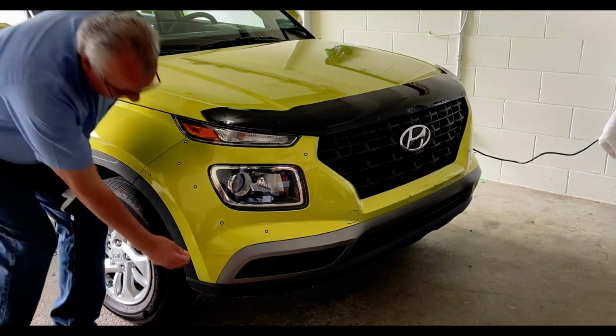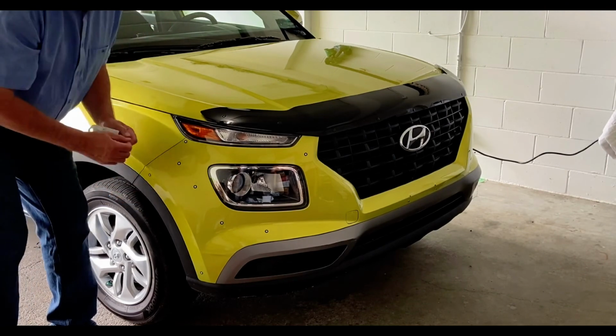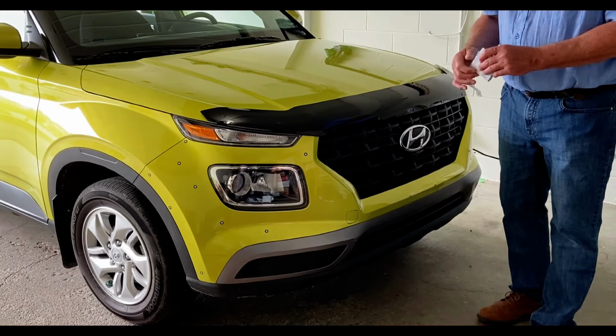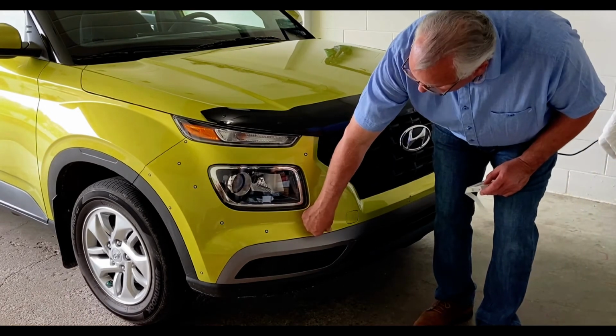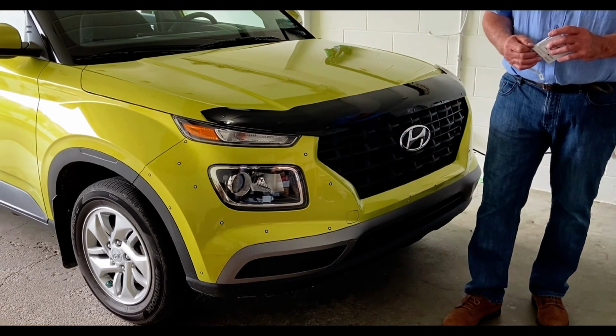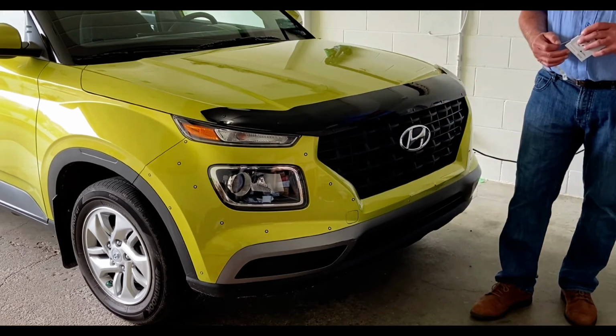The Peel 3D scanner can scan in 3 modes. One is a geometry mode, the second is a target and geometry mode, and the third is a texture mode, which will pick up color or textures. In this particular situation, we're going to use the geometry and target mode. The targets will assist us in helping to get a good scan.